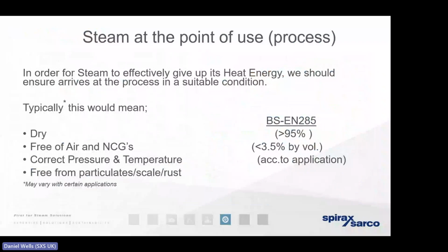Now, some processes, especially in the healthcare environment, are going to have critical applications. In building services, that's typically going to be the healthcare sector, which can use steam for purposes of humidification and sterilisation. And in those critical applications, it means that we're going to want to ensure that the steam is maintained at the appropriate condition.